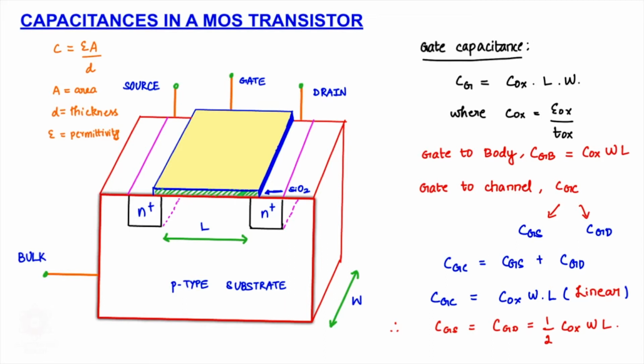MOS is nothing but a metal oxide semiconductor device wherein we have this gate metal as the metal portion, and we have the silicon dioxide layer which is going to act as a dielectric medium, and we have this semiconductor here which is partially conducting. Usually the parallel plate capacitor which we represent in MOS is based on the formation of channel. The channel is rich in electrons, and it is formed when the gate is induced with a particular amount of applied voltage.